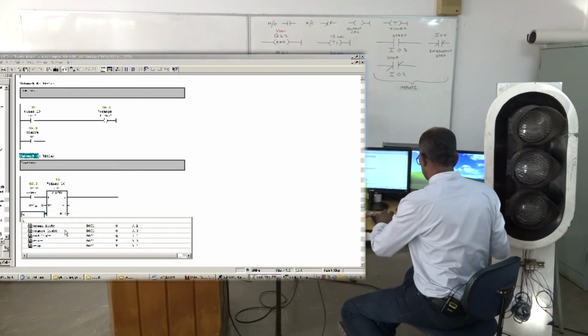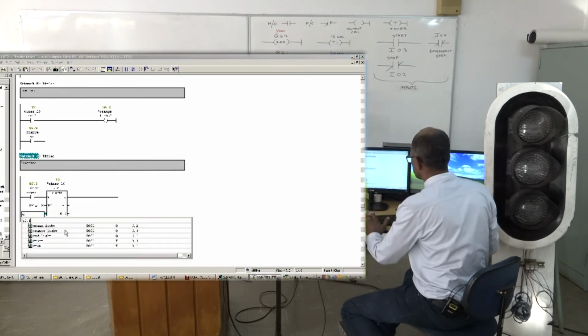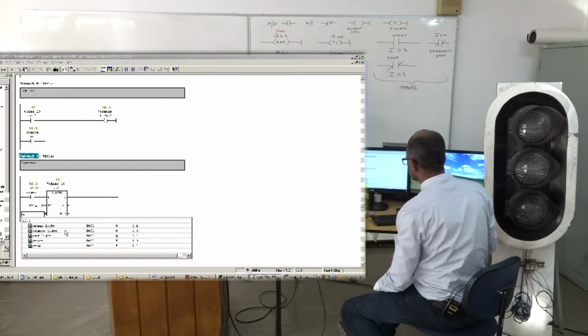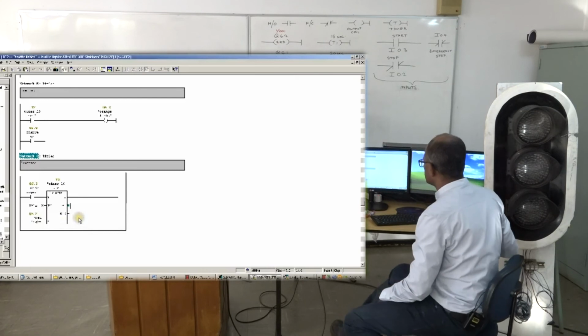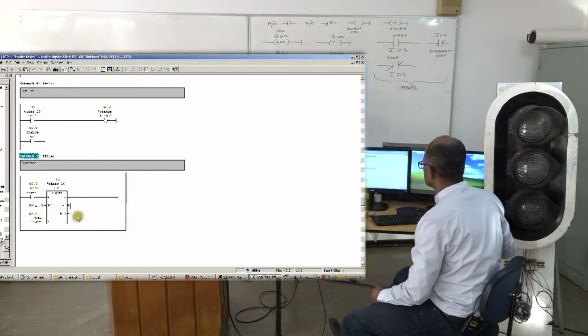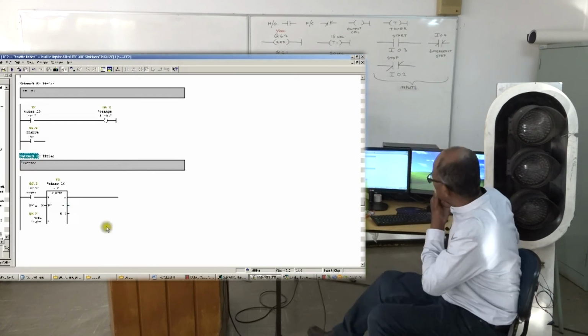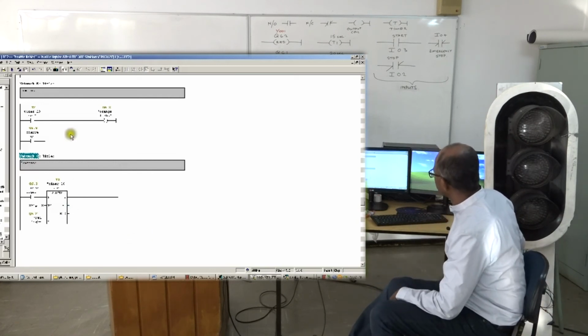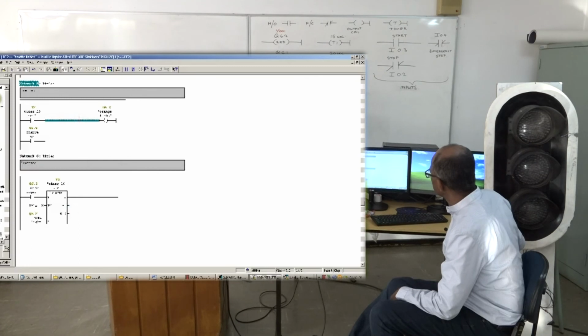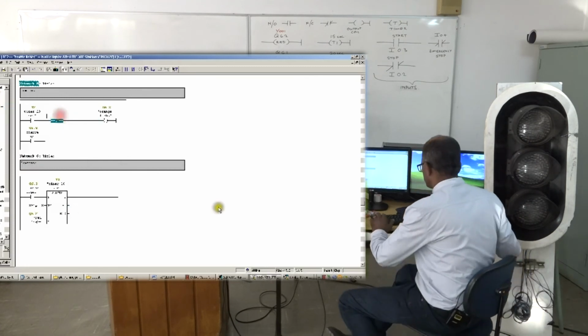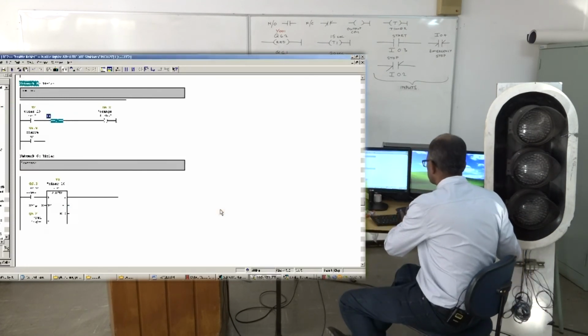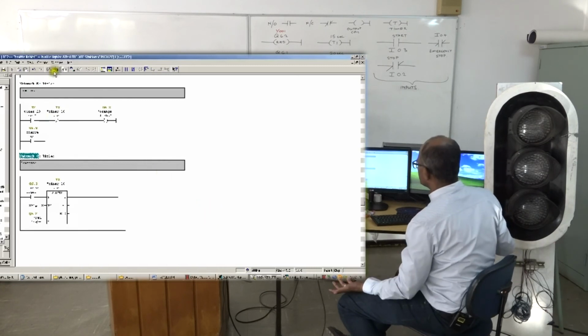So if I go back to line 1 of my programming, I can put the OR function and put in a switch and say, either the start button can start the red light, or T3 can start the red light.